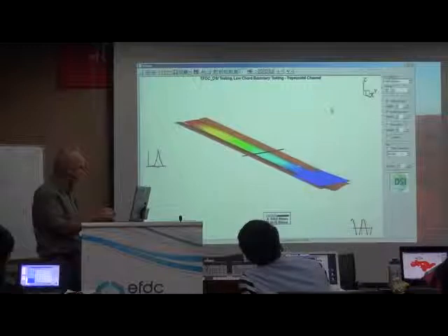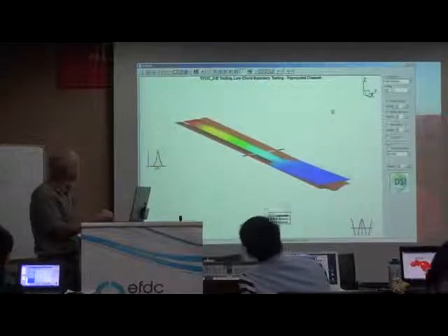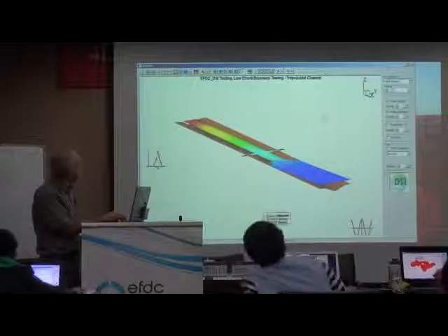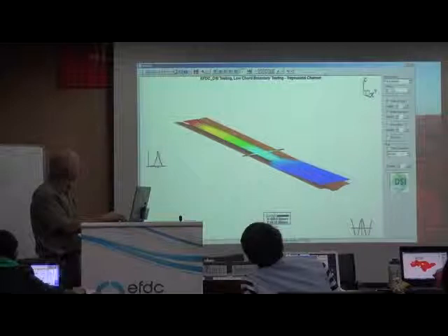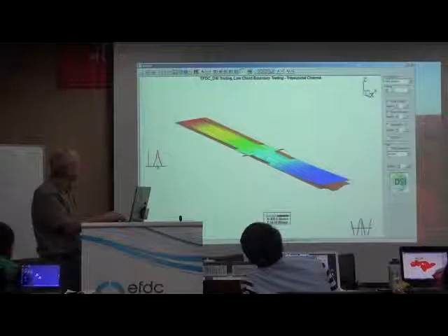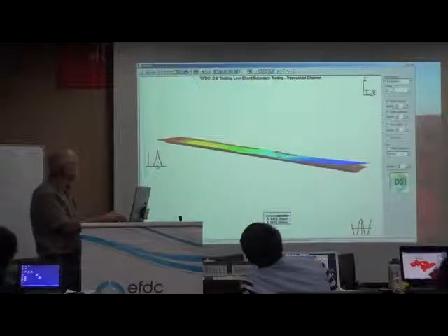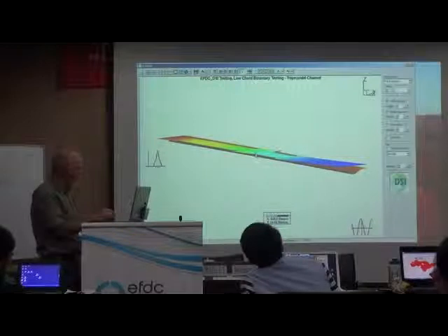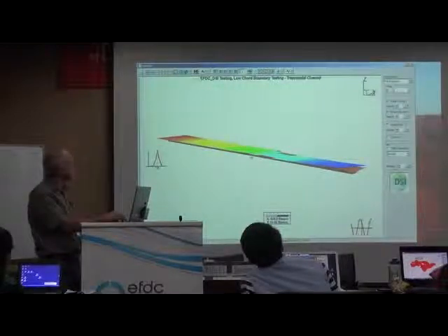And then as I step forward in time, I have a tide signal coming in from below, but the flood peak level coming in at the upstream boundary here begins to impact the bridge, and I start having overtopping of the bridge, and you can actually see a step in the water surface elevation due to the effect of the bridge here now.